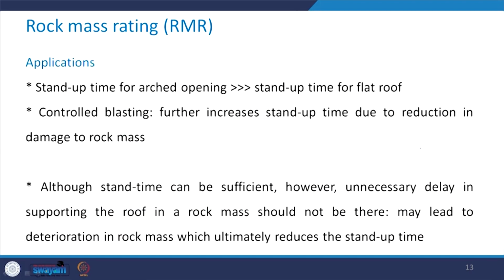Let us have some more discussion on this stand up time. The stand up time for an arched opening is much larger than the stand up time for a flat roof. What I mean to say is you can have this kind of tunnel cross section or you can have this kind of tunnel cross section, where in this case you have the arched roof and in this case you have the flat roof. So, the stand up time is going to be larger for this case as compared to this case.